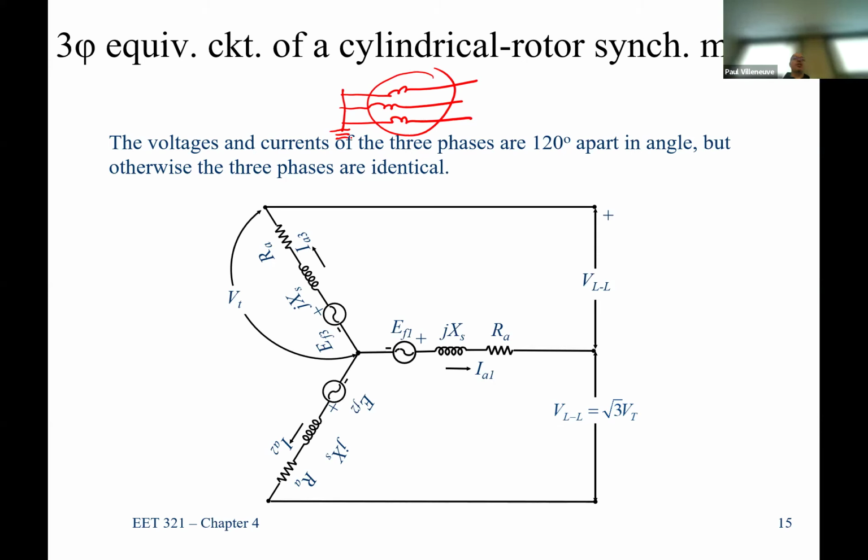So for every real world generator, this is called an AC elementary or a 3-line diagram. If you want to learn more about elementaries and stuff, you can take my 423 class. But these AC elementaries actually show how things are connected. And that shows you all three windings, because a lot of times you're monitoring these to be able to tell the health of the generator.